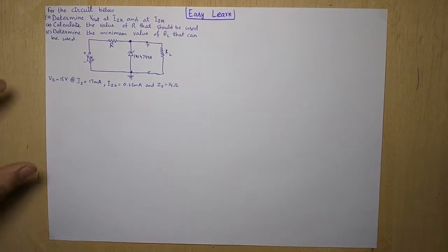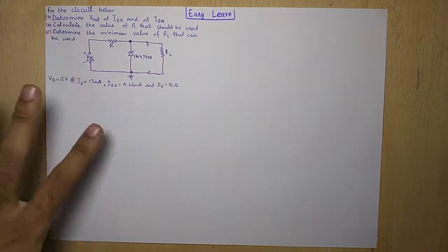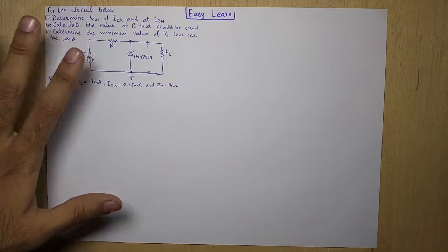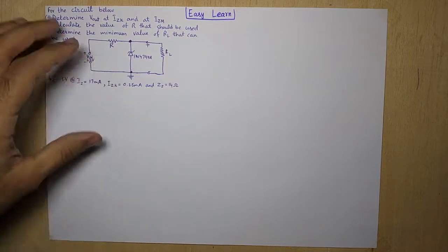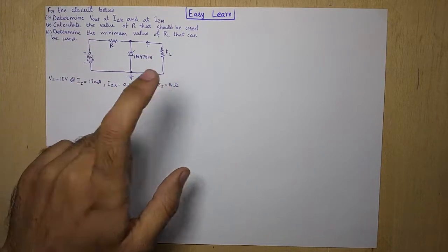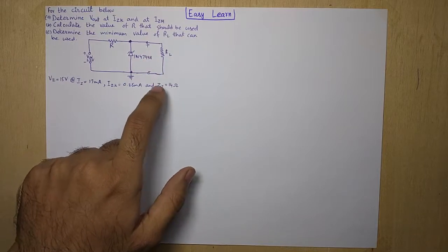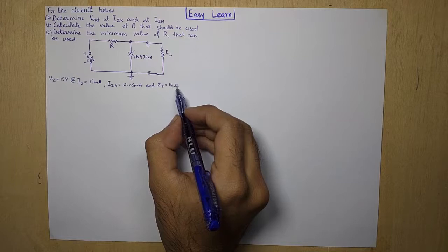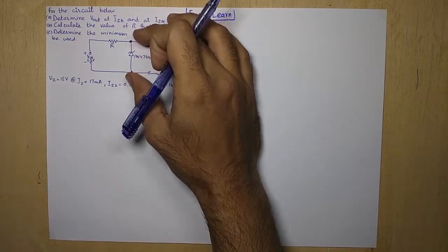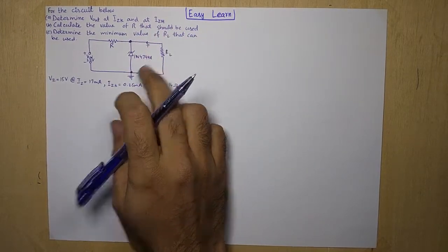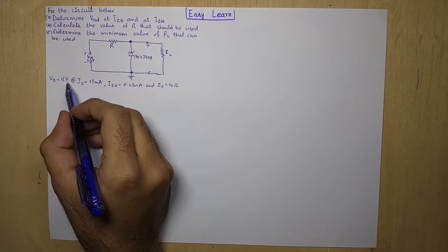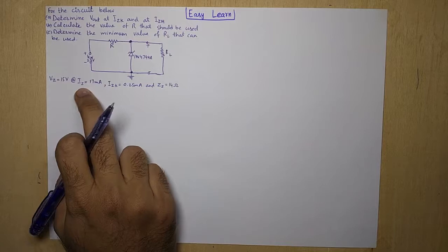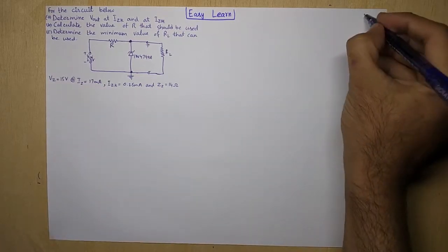In the previous episode, we discussed an example that included the ideal diode model, in which there is a constant output voltage that does not include the impedance. But in today's episode, we include impedance, which is in this case 14 ohm, and we use the 1N4744A, that is 15 volt and 1 watt, basically a regulator, and the IZ test current is 17 milliampere.